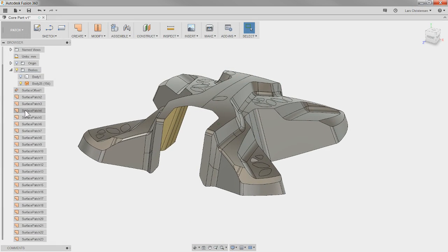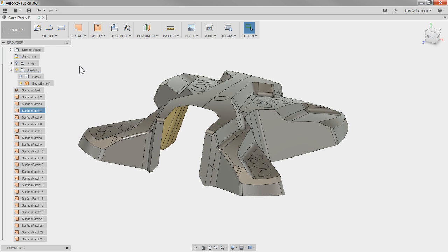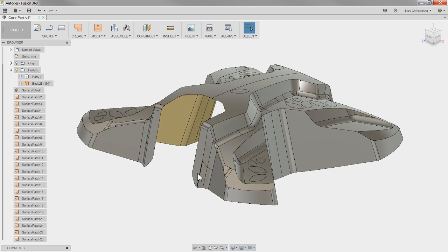And now I just wanted to show you how the direct editing thing is sitting. The problem with the direct editing is that I can delete them, but I can't go in and edit them or select geometry. Like if I right click here, I can delete it, but I can't go in and modify my settings and things like that. Now, I just wanted to show you, first of all, that it seems like Fusion works a little bit faster when you are in the direct editing mode. And many times if you're doing this, you maybe don't need the history, right? Like you don't even want all the different steps in a history line. So this will work okay.